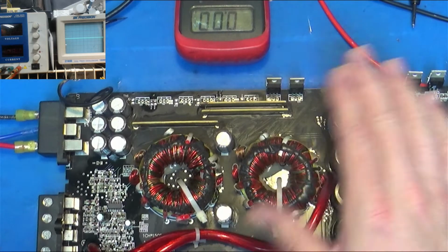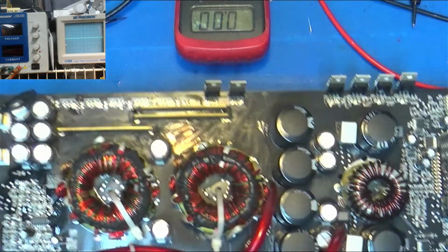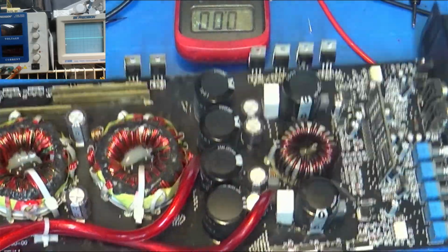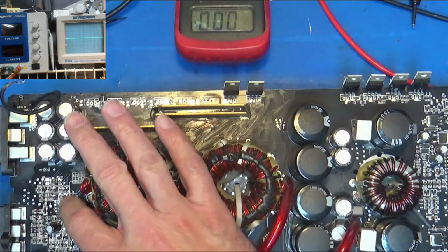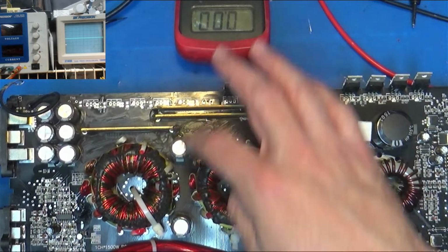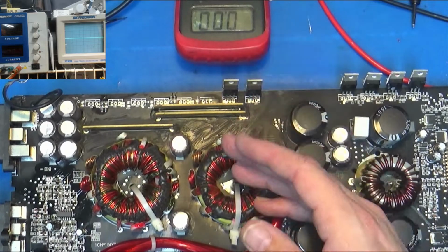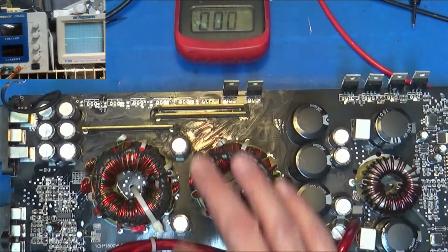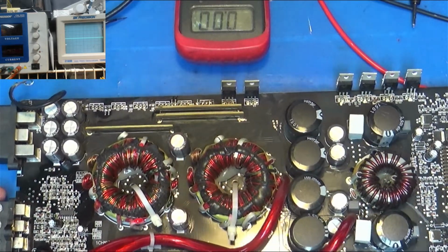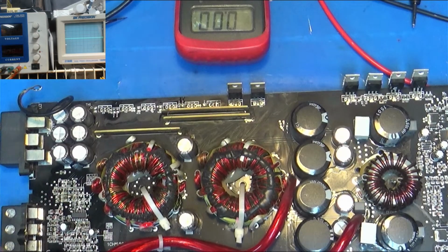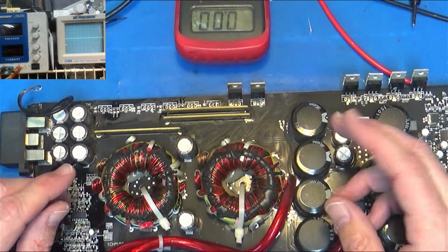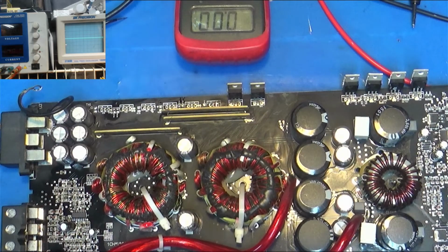Something else interesting happens because on this amp, if you watch the live stream, the output section did not show any shorts, so it may be just fine. So this may just be a matter of putting those back in, replacing the resistors that we took out and talked about in the live stream, and then putting in new 3205 FETs, and this thing will power up, and this amp should be good. So like I said, I'll bring you back if anything else crazy happens. Otherwise, this is just standard stuff that's in my other videos.